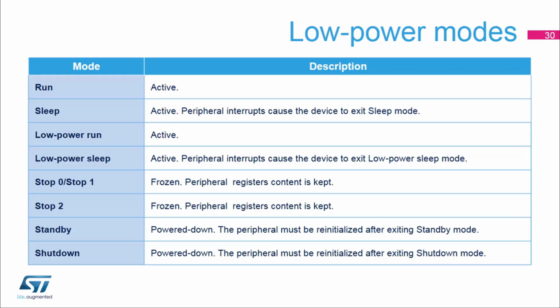The timer is active in any of the run and sleep modes, while it is frozen in stop mode. The timer state and register content are preserved, and the timer directly resumes operation when the MCU is awakened. In standby and shutdown modes, the timer is powered down and must be completely reinitialized when exiting from these modes.